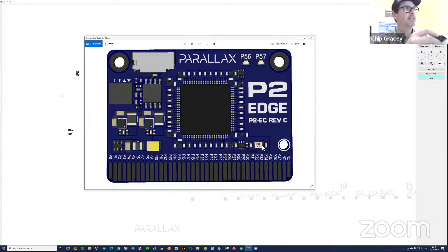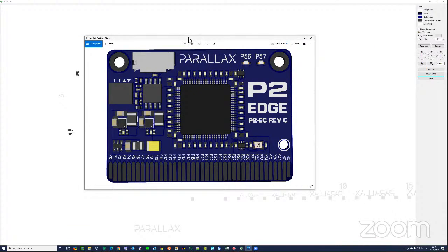Yeah, the oscillator. And we're also getting away from these, this won't focus, but these little ceramic inductors break easily. Like I just dropped this on my table when I was talking to Michael the other day, and it chipped off, probably changing its inductance. So these new inductors are molded, so they can't suffer these problems.